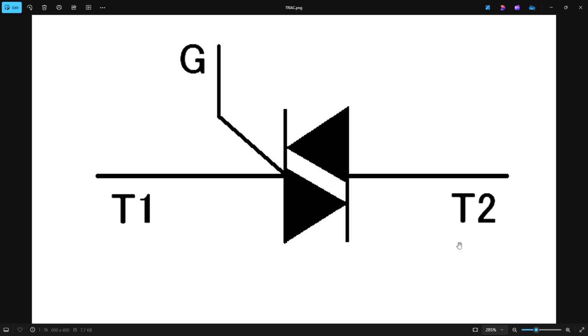Now, Triacs operate very differently than most semiconductor devices. You can't think of them as a MOSFET. A MOSFET, when you put voltage to the gate, turns on and lets current flow one direction through the transistor, and turning the gate voltage off would stop your flow. That won't necessarily happen with a Triac. Turning the voltage off the gate does not make the Triac stop conducting, at least not immediately. You don't have complete control of when this turns off. You only have control of when it turns on. So let me explain that part of it.